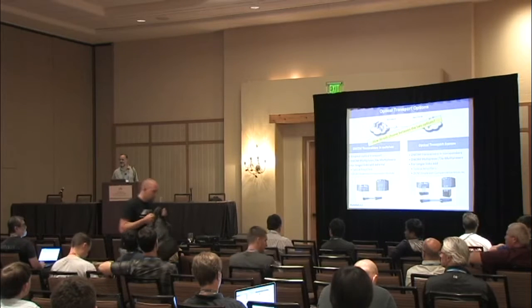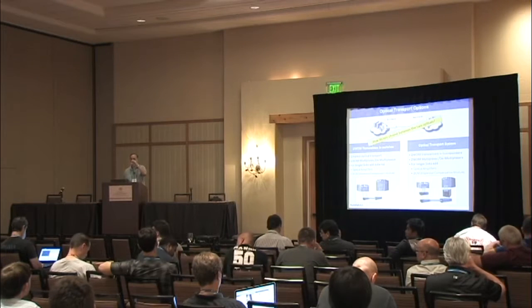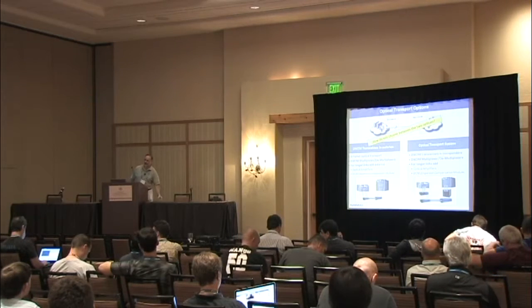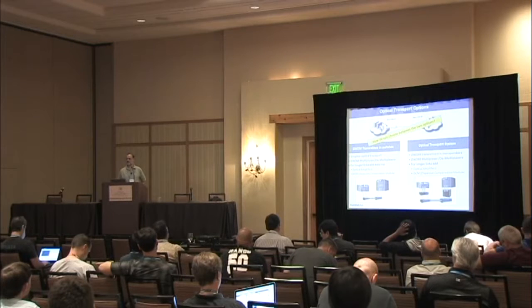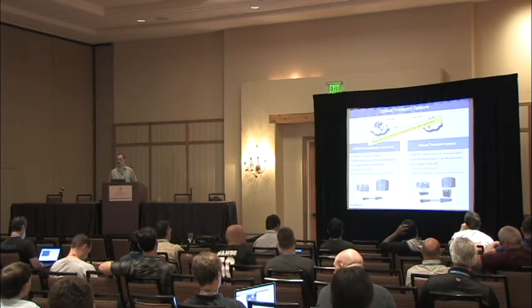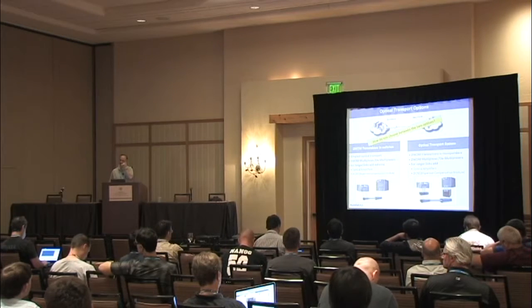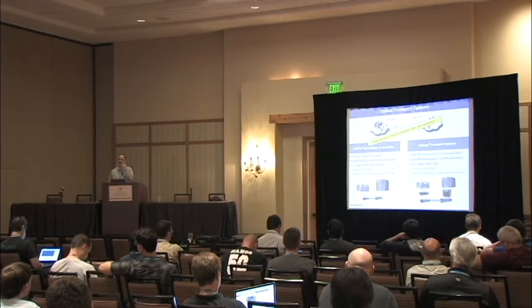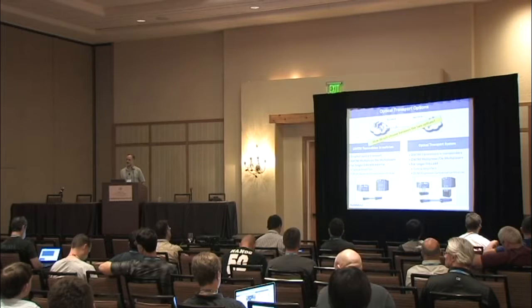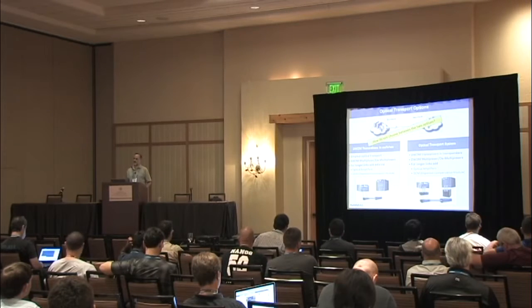It's application dependent which one you're going to use. But as far as what reason would you have to choose one over the other? If you're in a short span, doing that very simply. Absolutely. If you're going long haul, if you have a need to drop a wave out in the middle, then you may not want to. You're going to be forced to have some electronics in there. If all your channels are going from one spot to the next, if you're designing a hub and spoke something, then the DWDM optics will still work.